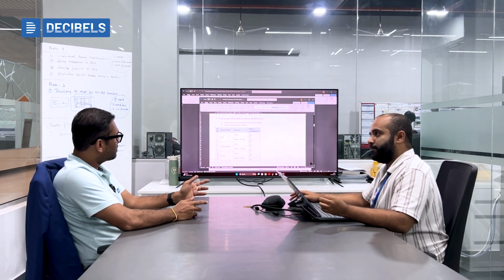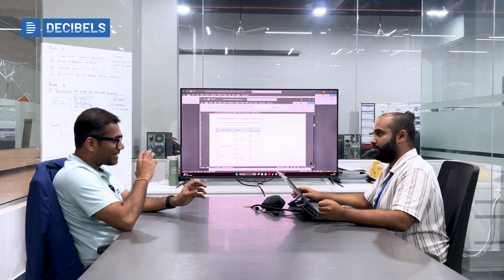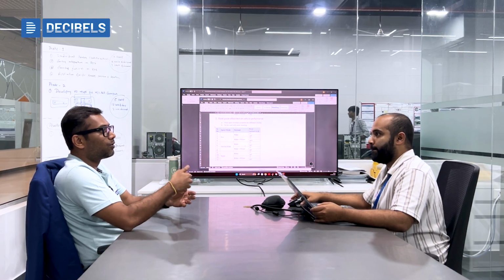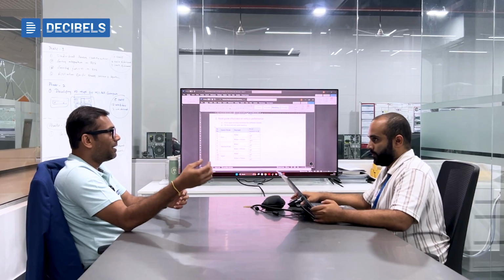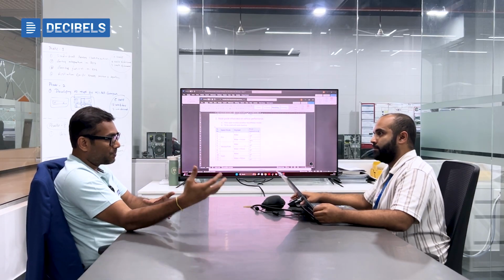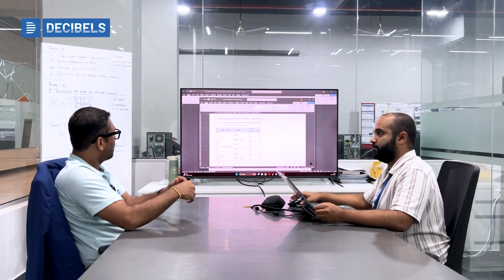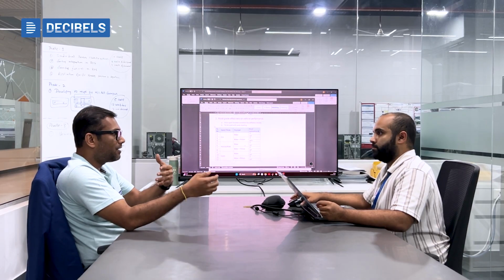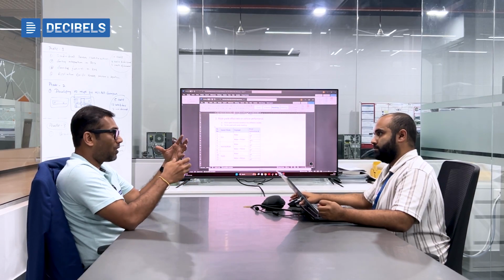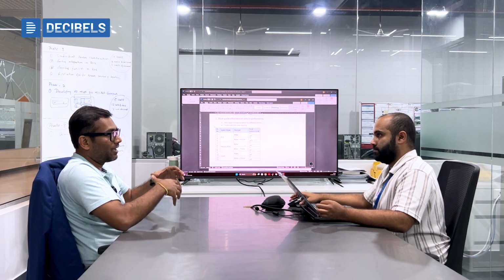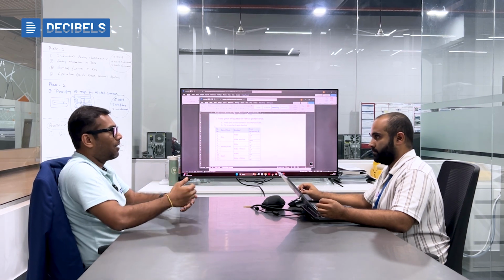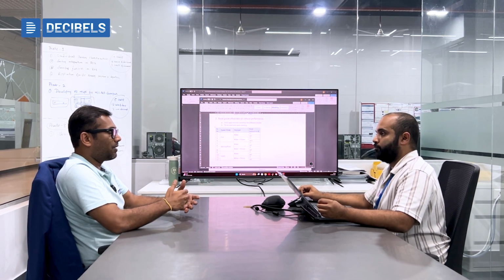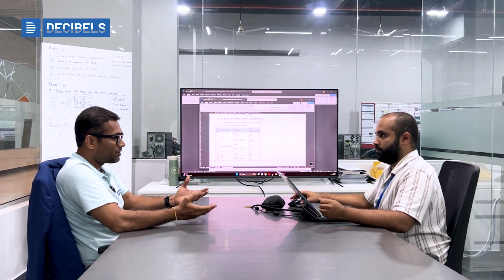So if I understand, with the acceleration, we are trying to see if the vehicle can perform in the same way with rider plus pillion and such scenarios. Here we are also trying to see, if the 7-degree gradient is there, if the 14-degree gradient is there, if there is one person, if there are two people, how the vehicle will perform in terms of gradeability, and also in terms of acceleration.